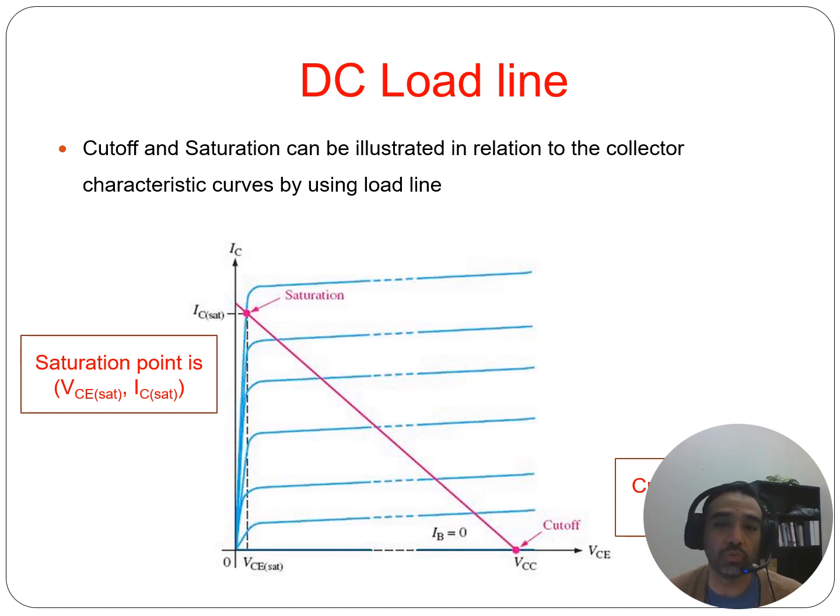So if you want to learn how to use the graph, you want to draw the load line. You draw the load line by plotting the maximum and minimum points of IC, the collector current, and VCE as well, based on the circuit that you've designed. And so your load line is going to be specific to your circuit, and obviously the components that you have in your circuit will determine all that.